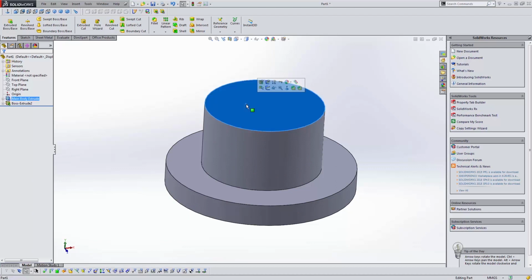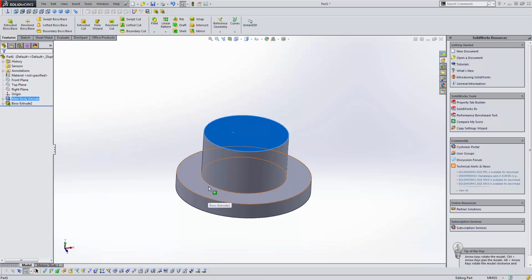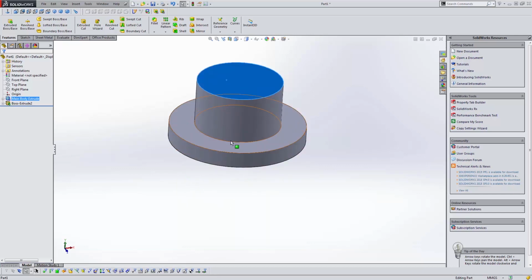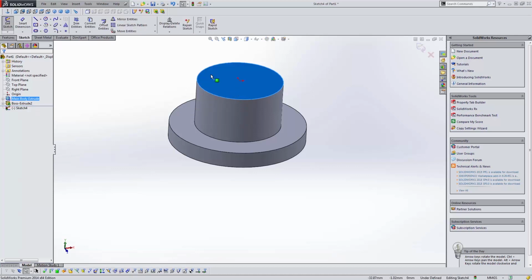Now the next thing I need to do is cut a hole into this for my threads, because basically this ends up being a threaded hole here with a bottle that you put on the top, and then it lets water down into these little troughs that we're going to make, and it feeds the ants. So same thing, I'm going to click the face, and I'll hit S, the shortcut for my tools again. I'm not in a sketch, so it's going to give me what features I want to use. I want to use the Extruded Cut.